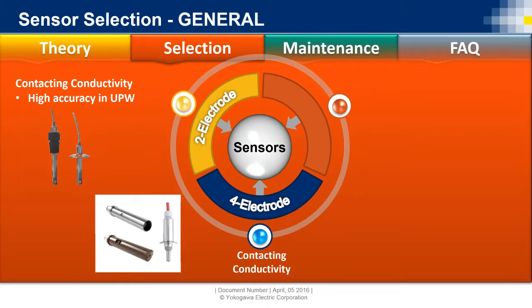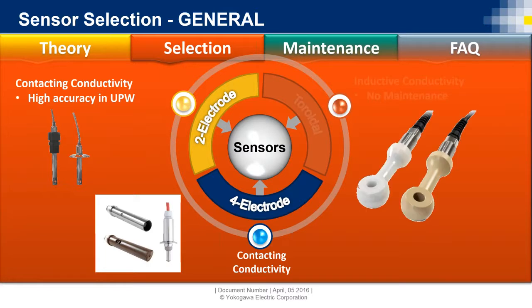Another style is this one here, the Hamilton one. You can kind of see it on here, but it has the PEEK material at the bottom, and then it has a metal pole. On this side we can only see 2, but on the other side there's 2 more. So those poles are the same thing as what would be inside those other sensors, that have the ions that respond and react, so that we can generate and read the voltage that's generated.